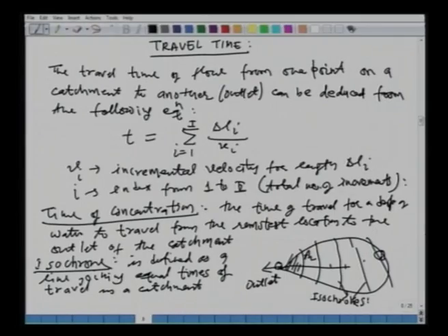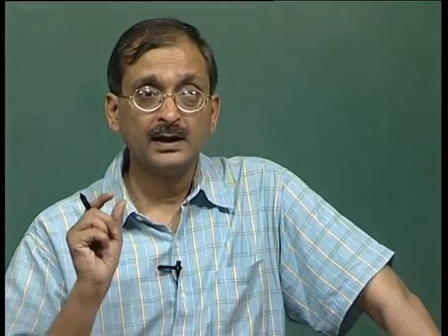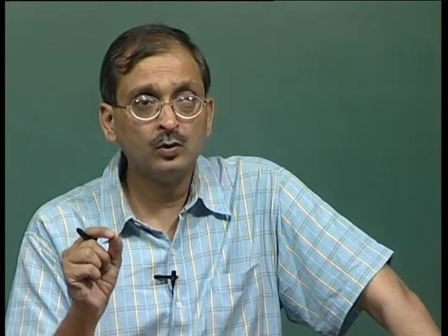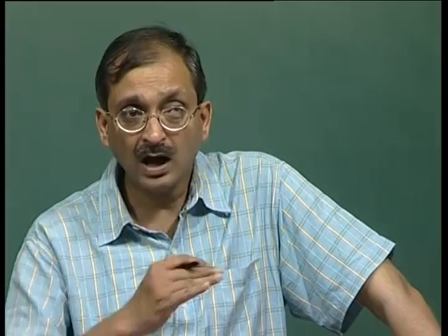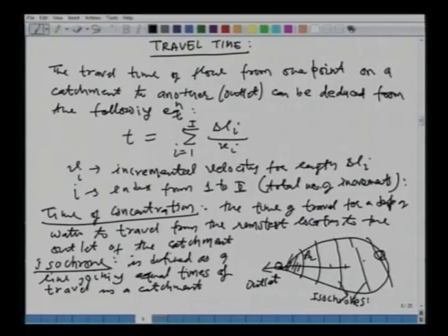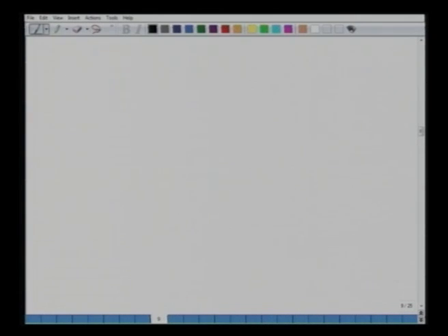The next one, A2, we say is going to take 2 hours, or twice delta t, and so on. With that you see that whatever input is falling on the catchment, we would be able to translate that input in time, so that we will be able to find the direct runoff hydrograph response, how the shape of the hydrograph would be. Let us move on and first look at the concept of how we can calculate the direct runoff hydrograph from what is called a time area diagram.